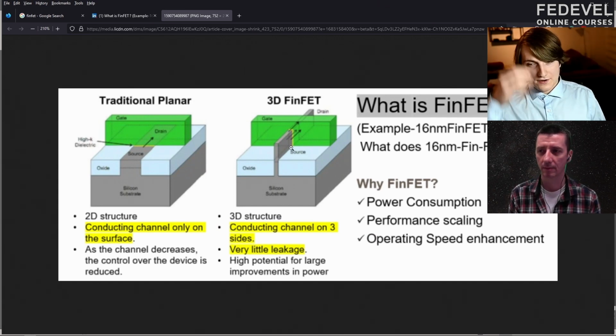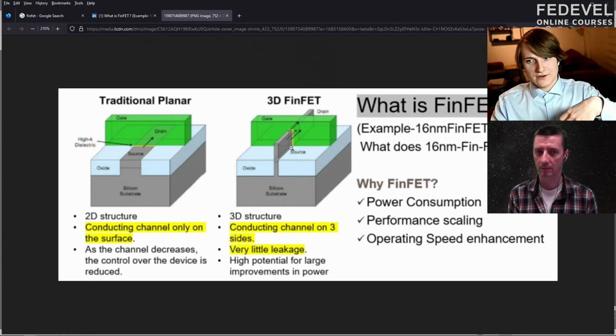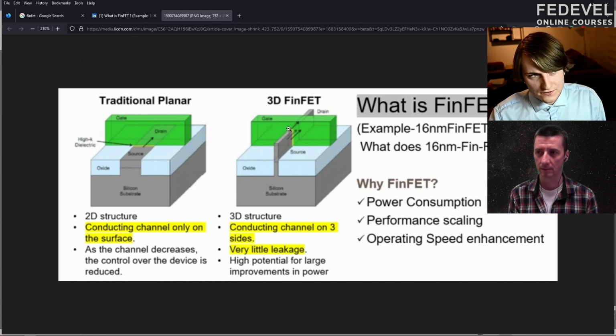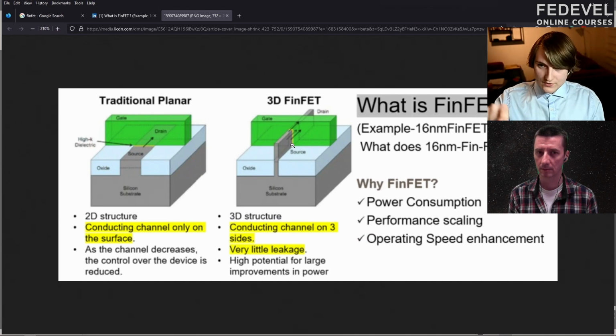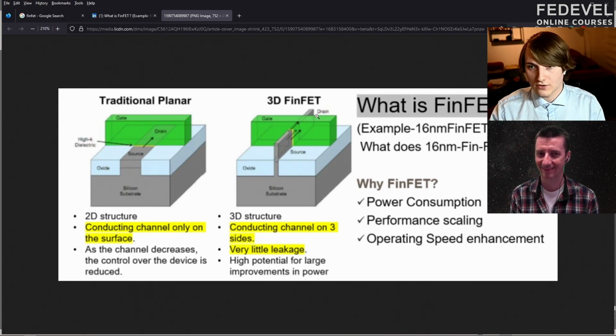And then, when you go after that, they're now looking at... I think TSMC for their next generation is going to go to gate all round. So instead of having a fin, you have a little bar that is wrapped in the gate. So it wouldn't be connected here at the bottom. It would just be a little rod that goes from the left to the right, and you can then put multiple bars on top of each other to make more transistors. And that's gate all round. But that's in research. There's no one who I think commercially has this available yet.